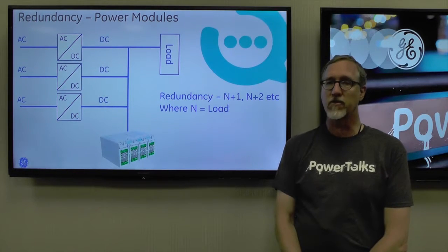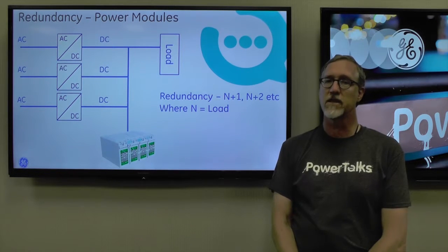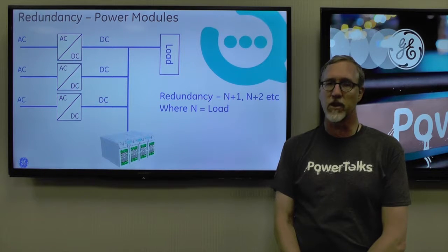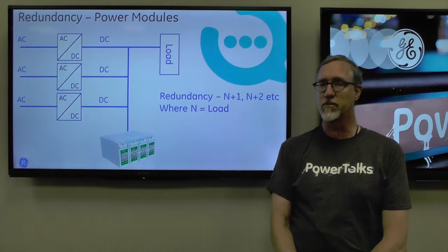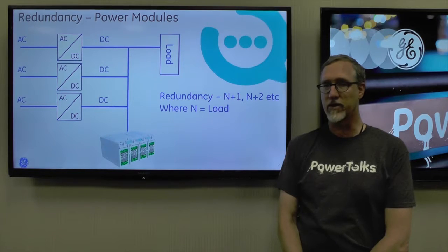It is important that rectifiers are connected to the bus through a fail-safe switch, usually a FET, so that failure of a component in the rectifier does not compromise the impedance seen at the bus by the other rectifiers.